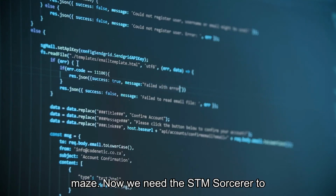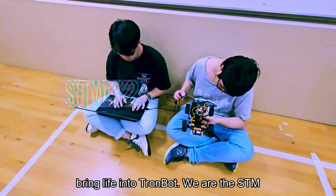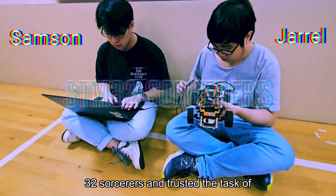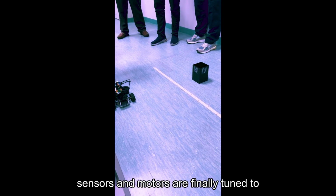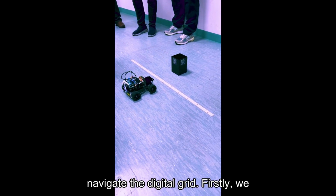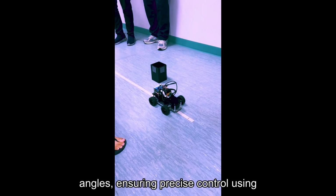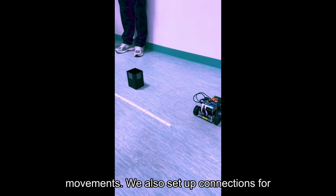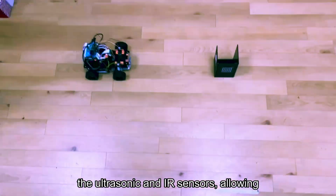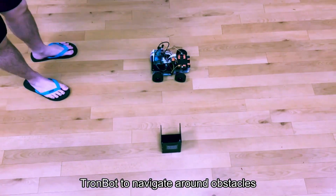Now, we need the STM sorcerer to bring life into TronBot. We are the STM32 sorcerers entrusted with the task of configuring the hardware that powers TronBot. We have to ensure that TronBot sensors and motors are finely tuned to navigate the digital grid. Firstly, we calibrated the servo motor turning angles, ensuring precise control using the gyrometer and PID controller, and adjusted PWM values for smoother motor movements. We also set up connections for the ultrasonic and IR sensors, allowing TronBot to navigate around obstacles accurately.